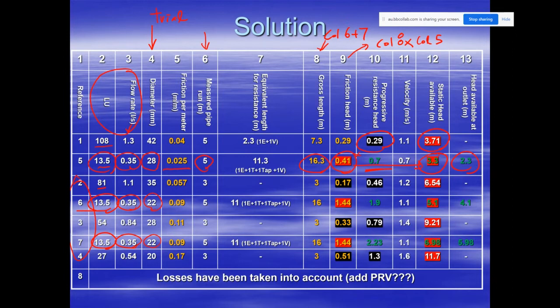As a good engineer, we may use this approach to check the discharge pressure head. Now, frankly speaking, in this table, you have set 5.98 meter head discharge pressure? No, too high. Am I correct? It's because you are set about 3 meter head, maximum 4, but this is nearly 6. That means we get trouble.